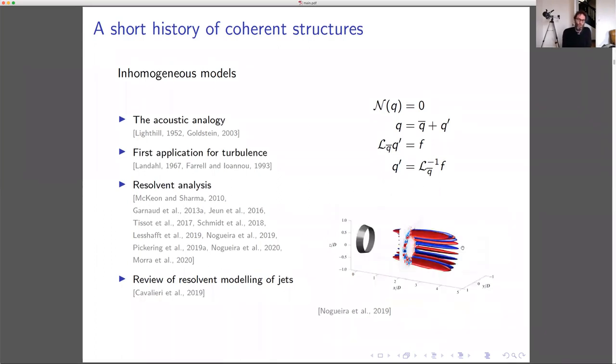If you then reduce the frequency and look at higher order azimuthal modes, you see these streaky structures. This was done by Petrônio Nogueira and others last year. And this is showing, again, these modes come from the linear operator. They compare very nicely with the experiments that we performed. And this basically showed us that the lift-up mechanism that we're more used to thinking about in wall-bounded flows is also active in turbulent jets.